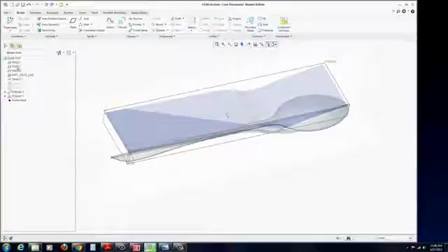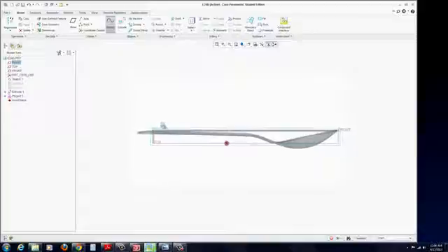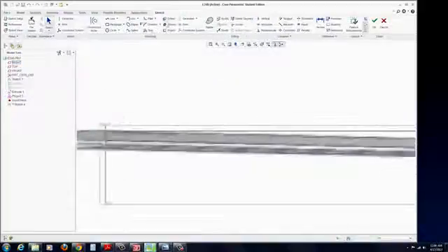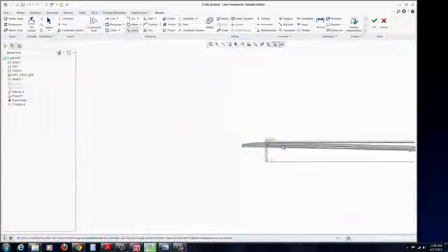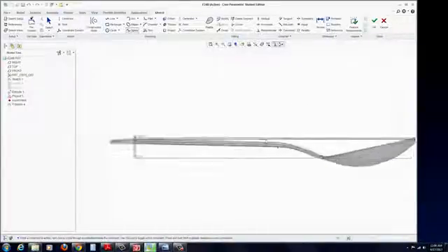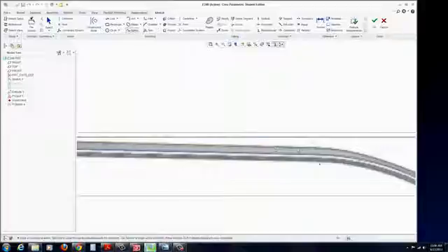Now we need to select the right plane again, start a new sketch, and we're going to draw this next center line, this next spline up at the top here, and follow that through and get away from that center line as soon as you can. As you saw, I accidentally snapped to it earlier. Start putting in several points when it gets to the bend.